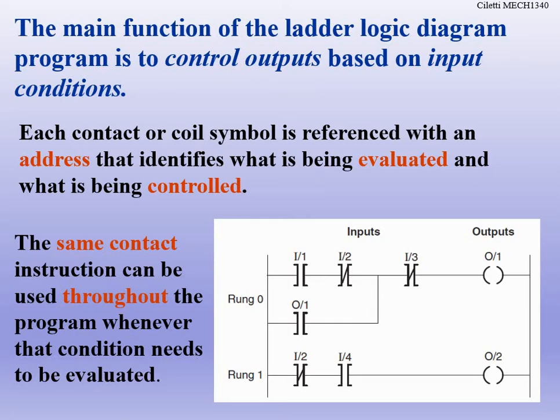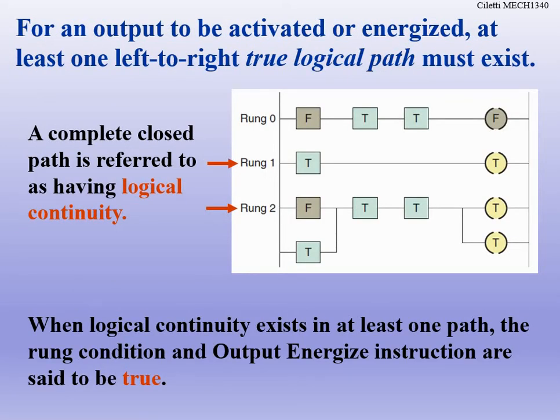So think back to station 1 on the 870, because that's what you're programming as part of your final. What has to happen? Well, the feed cylinder has to send a part in and retract, and then the pickup cylinder has to come down, and the vacuum has to come on to pick up the valve body. Then that has to retract, carry it over the linear traverse, set it down onto station 2, come back up, and return back home. You have to write the program that goes in that specific sequence, based on all the inputs and outputs, so that it can properly move the part from station 1 to station 2, and then start all over and do the automation. You have to go in a specific order, and specific things have to happen for the next step to occur. So just think about that as we start doing our programs. You're creating the path.